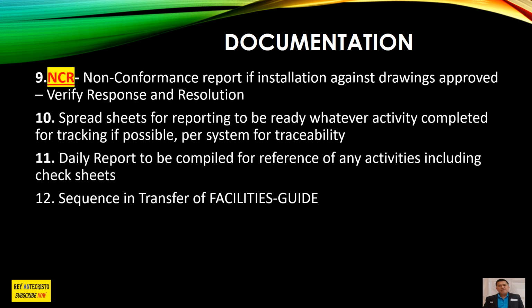For example, if you are working in ADNOC, all documents, all CDs downloaded, everything must be shifted to their main archive, and any superseded drawings must be marked as superseded. Any approved drawings and then any revised drawings, we have a stamp there. We can stamp as superseded so that the latest as-built drawing is the one that proceeds to the facilities.